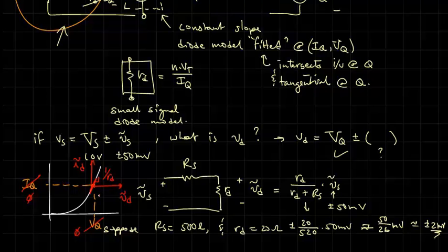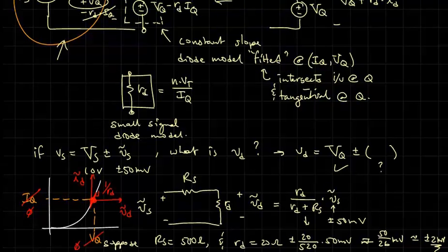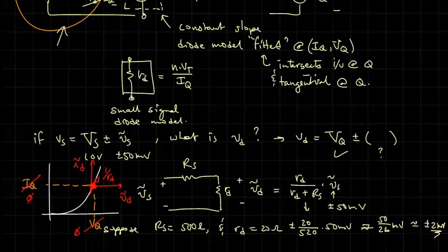Then I'll take that little small signal response, and I will add it back onto the operating point, remembering that after all, this little linear excursion, or perturbation, is actually riding on top of a larger operating point that is itself determined by solving ultimately the nonlinear diode equation. Okay, so there's an introduction to small signal modeling of the diode.